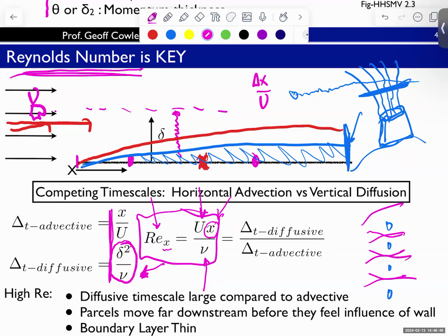So you have this region of dramatically slowed flow through the nets, which allows them to trap these particles. And in those cases, the thickness of the boundary layer relative to that hair size, or cilial hair size, is much thicker. The percent is something like 300 or 400% versus 1 or 2%. The only difference here being Reynolds number.